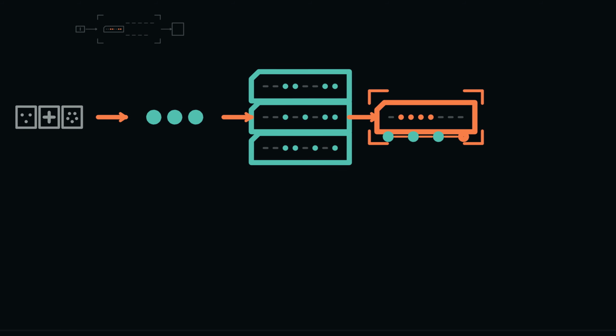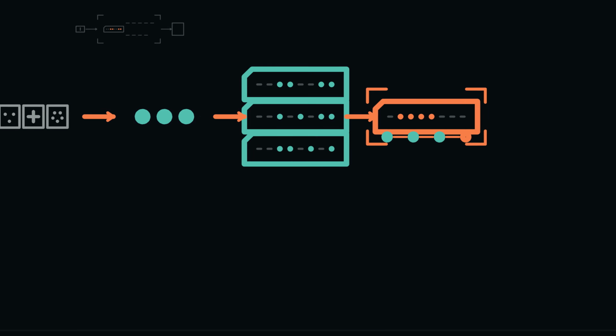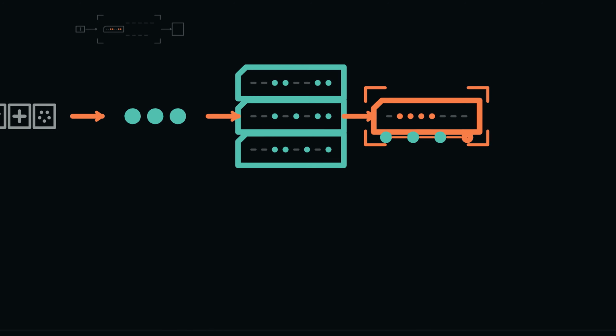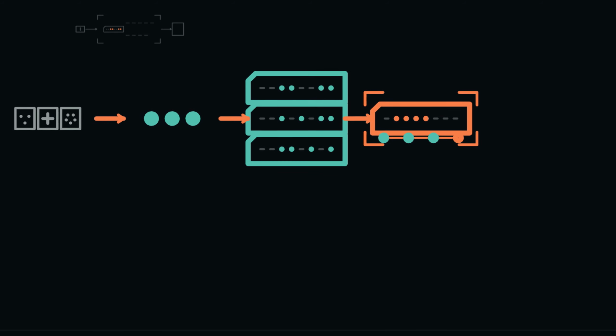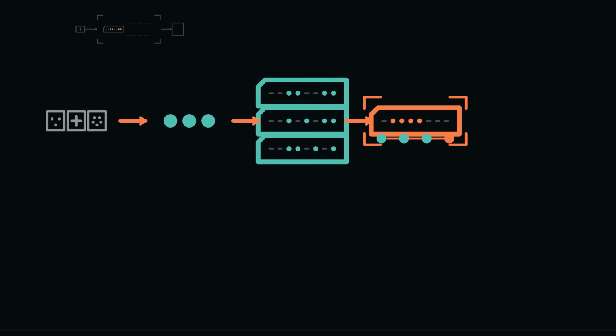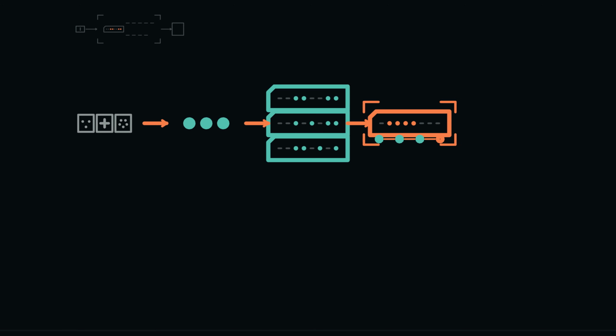Open 1 instruction fetch all the way. The program counter drives the bus, the memory address register captures it, and the decoder selects exactly 1 byte. Memory drives that byte into the memory data register. The first instruction register captures it as the program counter increments. The sequence repeats for the second byte, then Decode selects the operation and its operand. This same proven mechanism fetches each polling, conversion, comparison, branch, addition, and store instruction. Close the inset. The architectural transfer remains the same while the program advances.